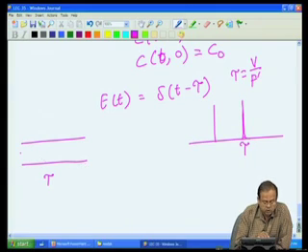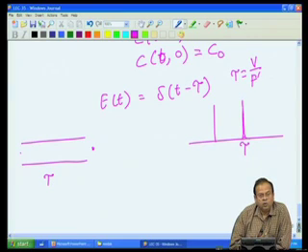Why? Because it is a plug flow. So, this tracer will move like a plug for an amount of time equal to the residence time, and then it will come out of the reactor in a single shot, because once again there is no actual mixing in the reactor.